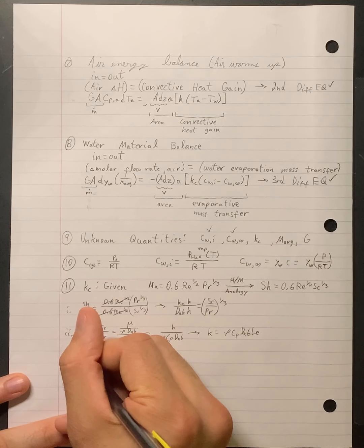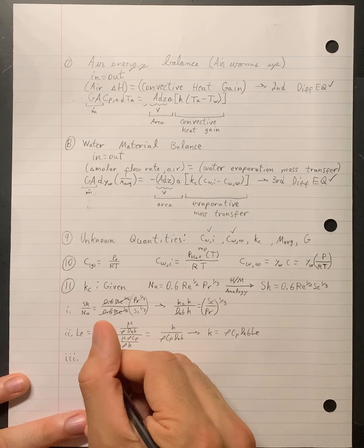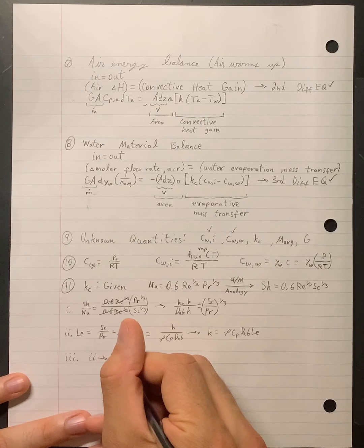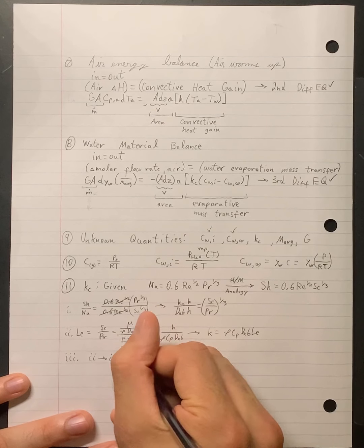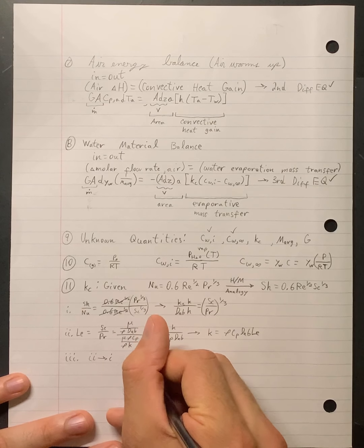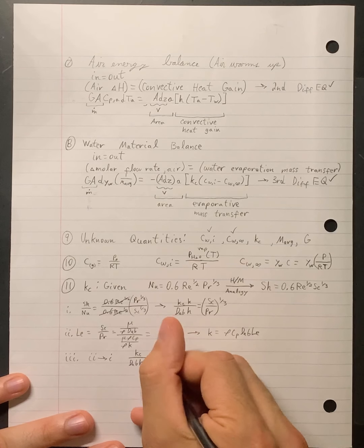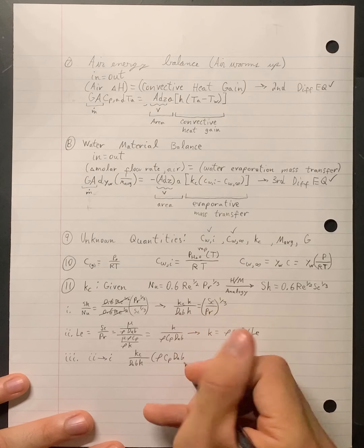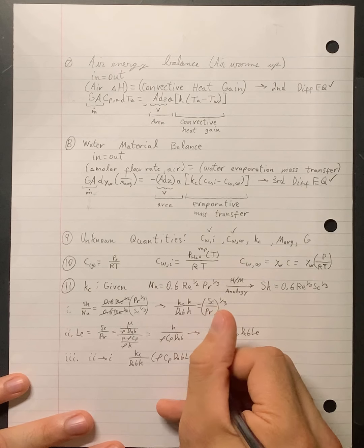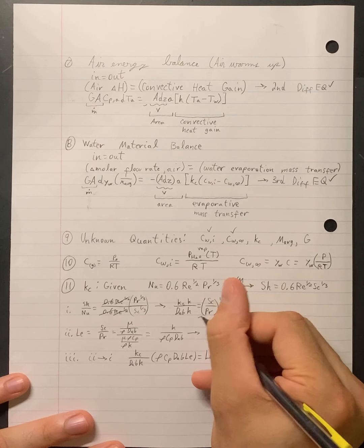Now for step 3 here, we can actually shove these two together, so shove 2 into the first one. This gives us Kc over diffusion coefficient times heat transfer coefficient times the density, heat capacity, diffusion coefficient, Lewis number equals the Lewis number to the 1/3, which is this term here.